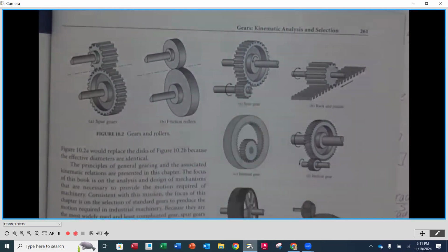They also are going to have a certain type of a tooth, which we will look at very, very soon. It's called an involute tooth profile, and it's the most common, most widely used type of gear. We are going to be focusing on those for that reason, but also the relationships that are developed are still going to cross over to the other gears. There's just going to be a little different nuances on calculations as you look at different sizes and calculating centers and things.